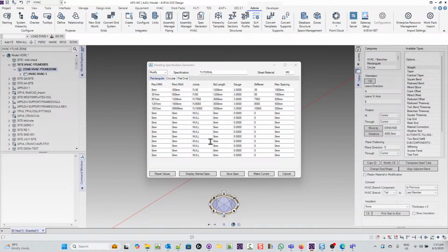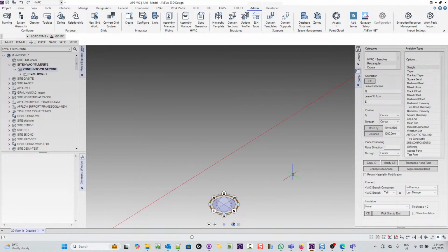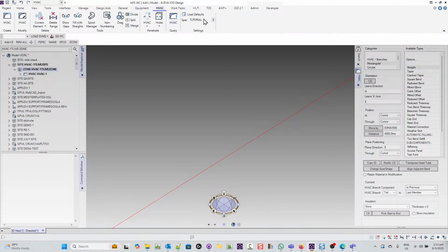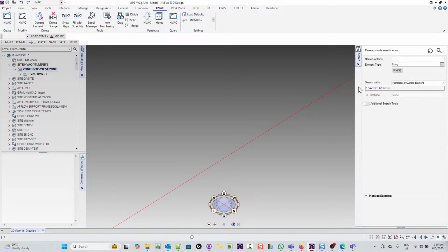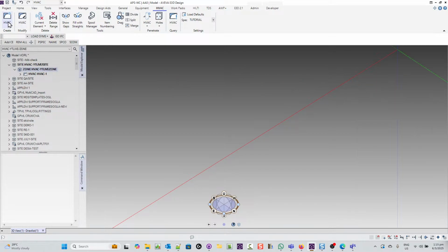This is how HVAC works, because HVAC works all by using design parameters. So therefore, you only restrict the length and so on for you. Okay, so this is the spec. So when you go into HVAC, you have to select your specification. So to start off, we do a create HVAC. I'm just going to close my other windows, and I'm going to say create HVAC.